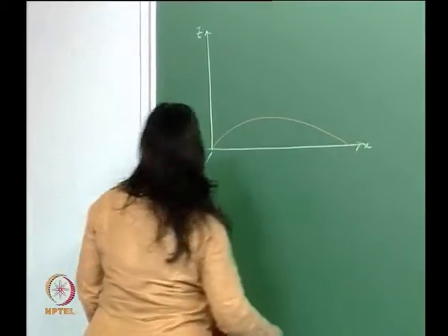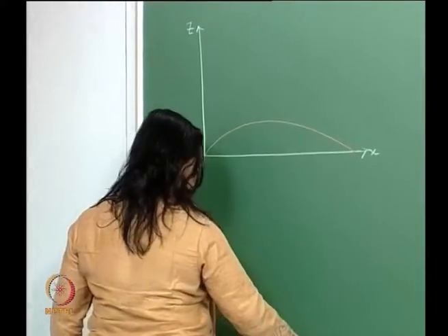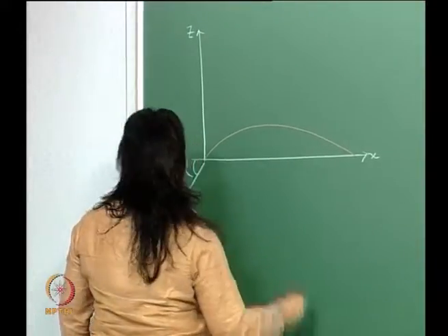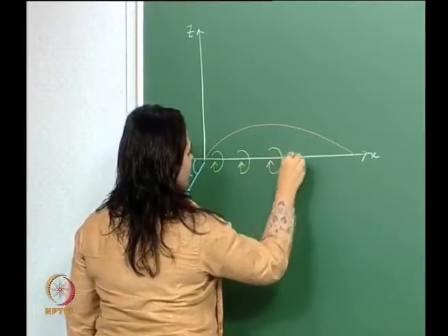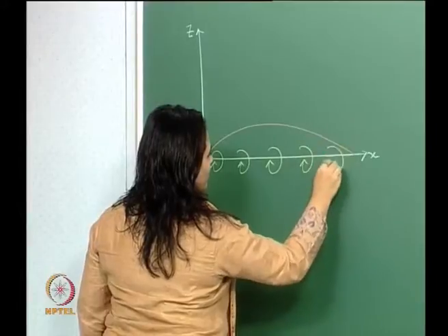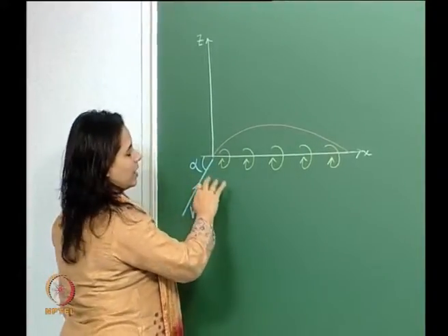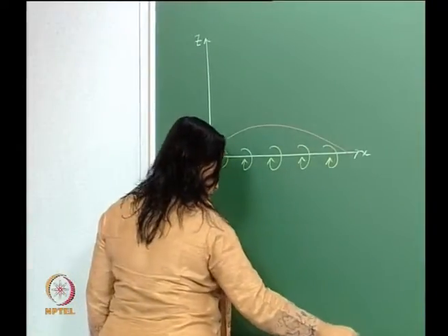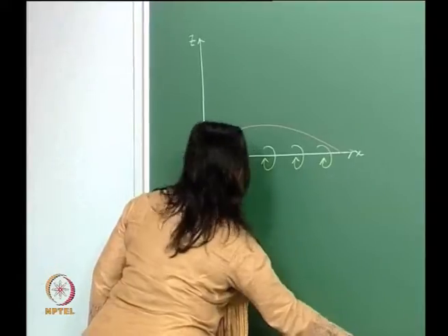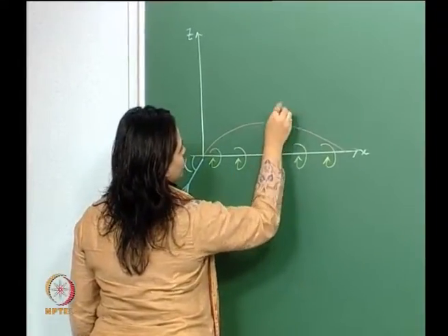This is the camber line that we are looking at when I say here. So, for a thin airfoil, I am distributing my vortices on the x axis, but I am still satisfying the zero normal boundary condition on the streamline.